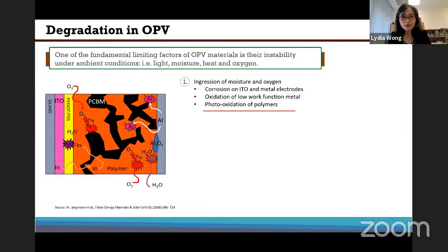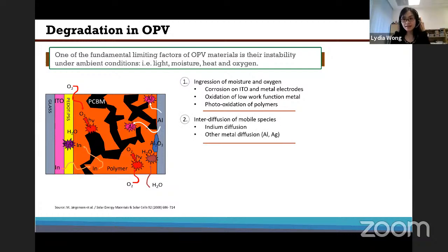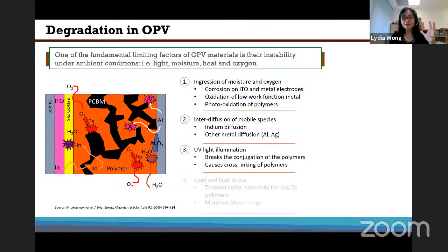Now the problem with organic photovoltaic is this is made of polymers, right? This is made of plastic. And if you notice, plastic doesn't last long. Your plastic can change color from transparent to yellowish, right? This is what happened with organic photovoltaic because plastic absorbs UV, and this degrades the polymeric structure. Okay, so because of this, the overall lifetime of organic photovoltaic is low.